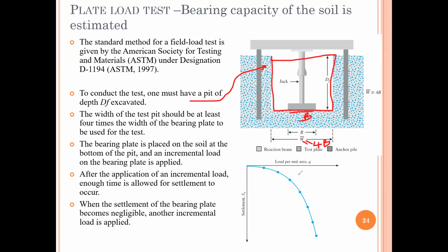And then with a hydraulic jack, like a vehicle jack, we can apply load. As we apply the load, we will be checking the settlement or the displacement. Once we apply the load, we check the displacement, the settlement.